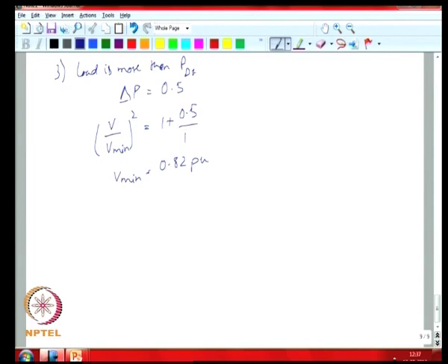So, next we will look at how you could make use of again the RLC model of the feeder, and then make decisions on whether there is an unintentional island or not based on frequency. So, depending on what your L and C values are, you can have frequencies which shift from your nominal frequency. So, based on the feeder model, we can write down expressions for what the change in frequency would be, and use that to determine whether an unintentional island has been formed. Okay, thank you.